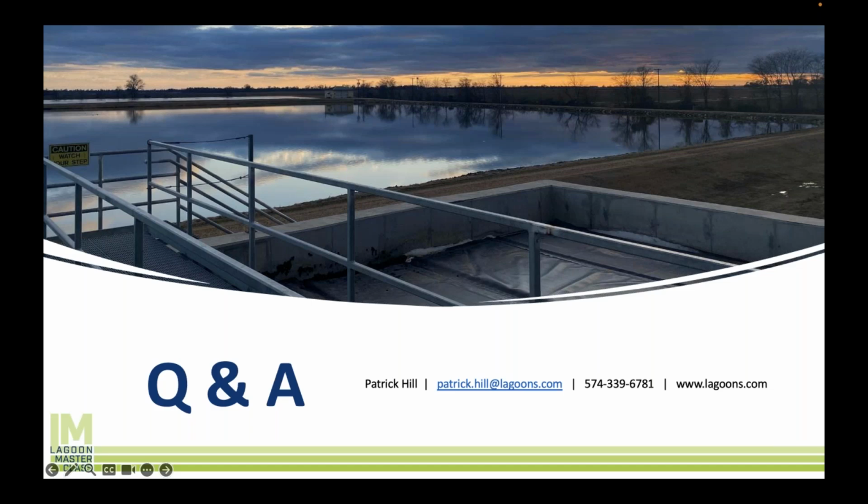Or if they die off and sink to the bottom, they get sequestered in the sludge blanket, which can rebound, but not all the time. Really long retention time lagoons get very natural denitrification, which is cool. But it depends on the site and lots of other factors.